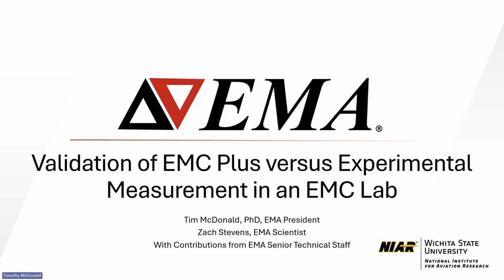Yes, so that's something very important. So often as we talk about this today, you've heard us say things about correlation with the testing. Because we had the chance to make measurements in the lab, we were able to do some things that maybe you wouldn't have done in a standard EMC test. For example, we had our partners at NIAR remeasure some things on a different day with the exact same unit. And the coupling results that they showed for some of those cases were pretty different. So we're repeating those measurements and we're getting some error bars on the measurement.